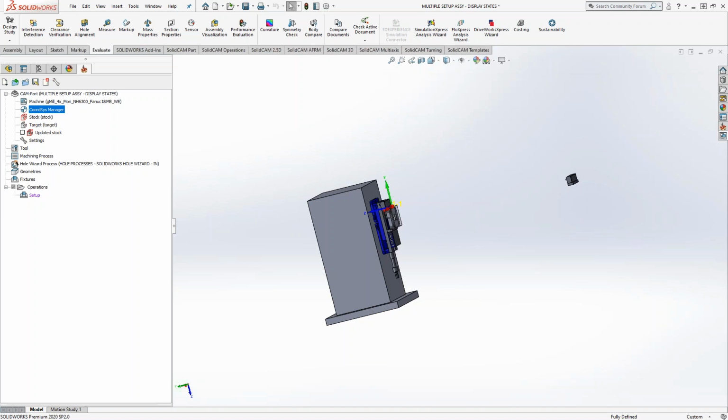So if you do a configuration where you've chosen a hole and then in another configuration it's no longer there, the toolpath will no longer see that piece of geometry, and it will want to be either recalculated to the fact that there's nothing there, or you might have to suppress that toolpath. But there are ways to program for things that disappear or reappear. That's a good example of what Kevin did in the KevCam this week. Those holes were eventually reduced in number or not even there at all, and that's when the toolpath just automatically updates itself to reflect the current status of the part file.